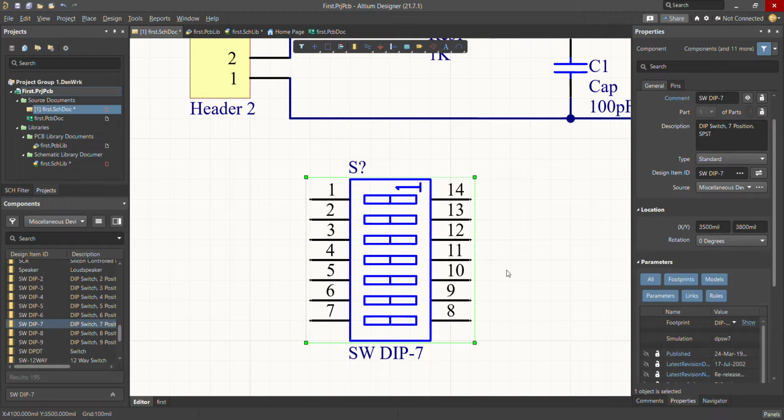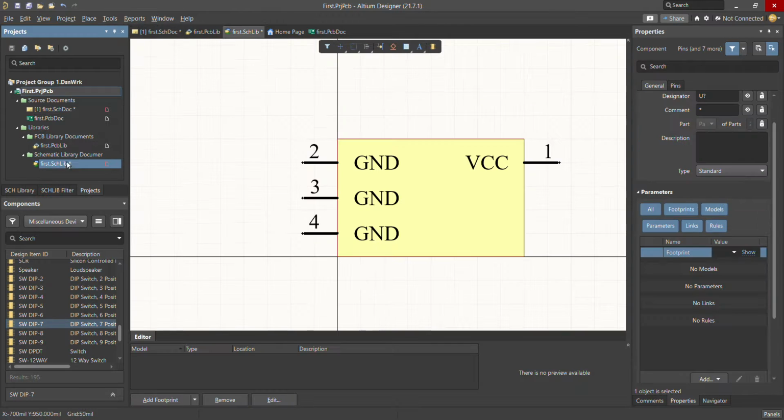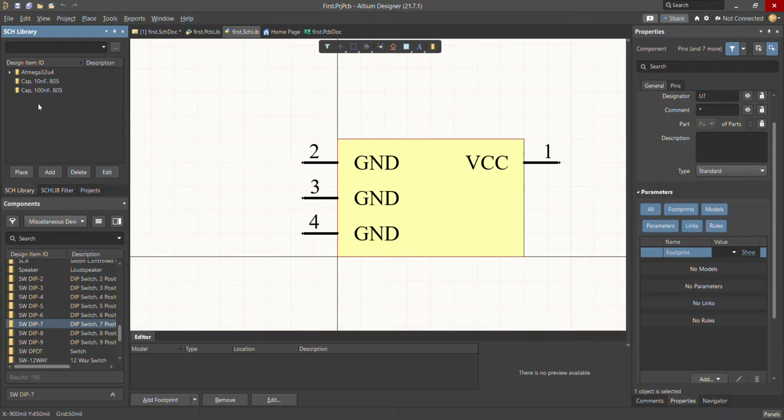You can just design them how I want. But let's say I'm just going to save this for now. And now we basically have our schematic library. Yes, I have to add a footprint for each component that we designed. But right now, we haven't learned how to do a PCB library design, which we are going to do next lecture. So you're just going to stick with the schematic library.